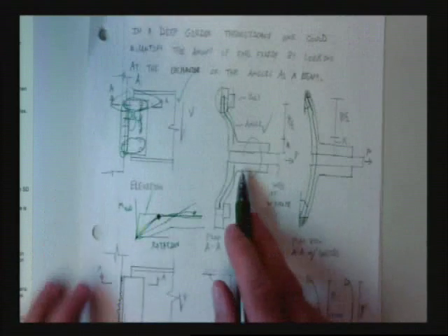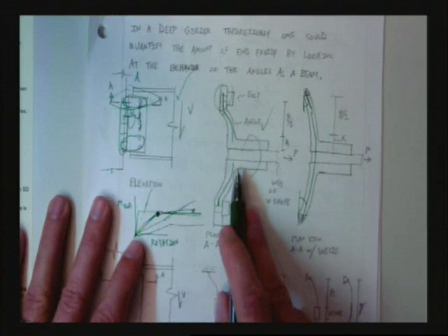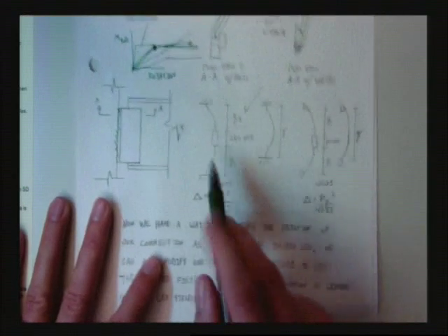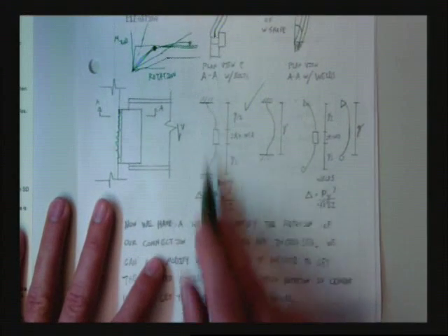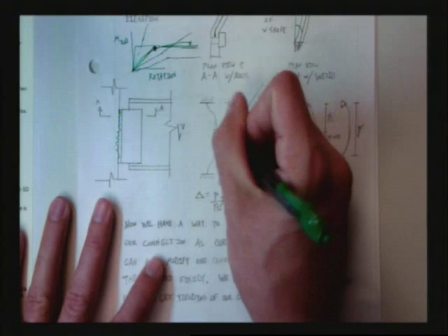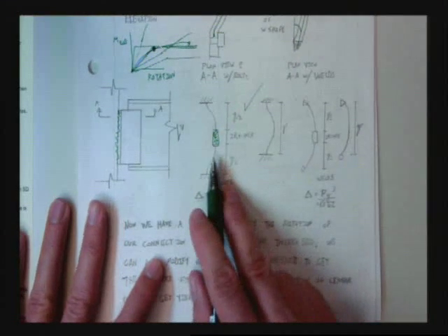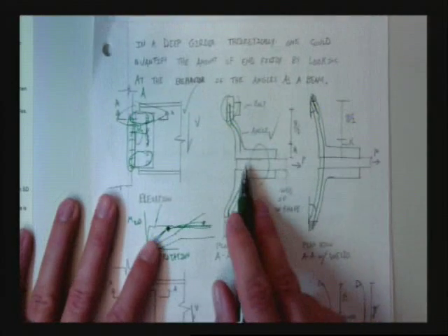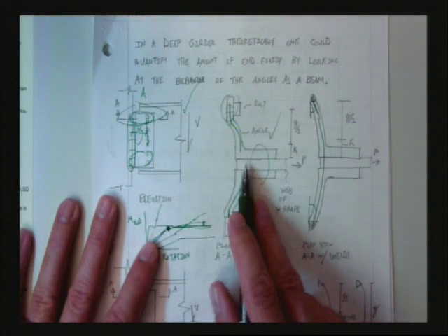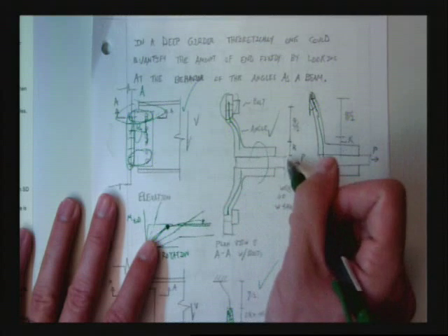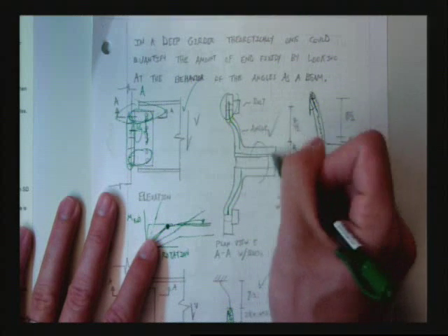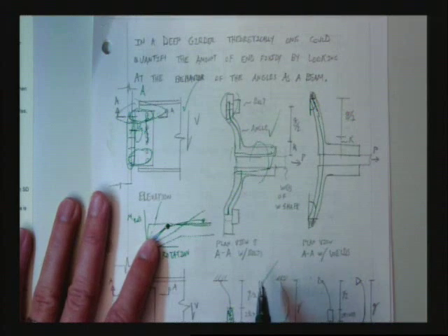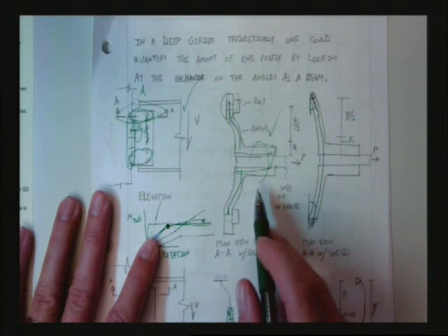Now, when I showed you this problem, you probably said, oh my gosh, I have no idea how to do this. And now when we simplify it, it looks like this. Now I have a fixed connection. Now I've drawn an infinitely rigid beam in the middle. Why did I do that? Well, we really do have that in a sense. We've got a super thick web. We've got a super thick flange here and a super thick flange. And is it truly infinitely stiff? No. But it's way more stiff.